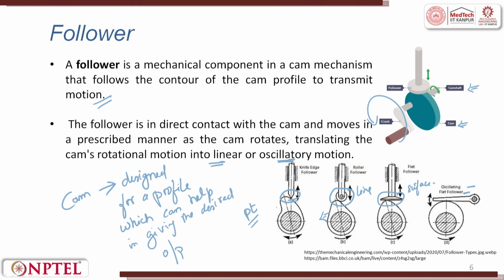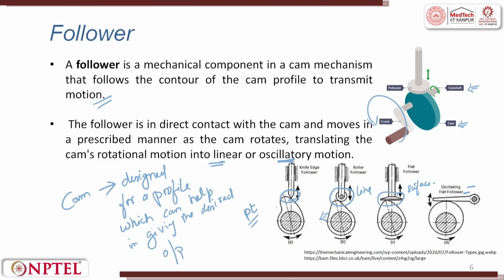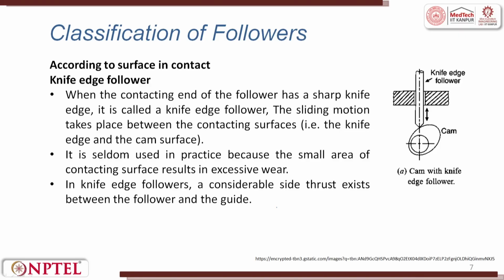Okay, what can be the cam material? It can be a metal, it can be non-metal such as a polymer. You can have this too. Can I have ceramic? Yes, but the only difficulty with ceramic is that it cannot take toughness or a fluctuating load. So, we try to give a ceramic coating on top of a metal and sometimes they call that ceramic cam and followers, but predominantly we will try to use metals. Again, in metals it can be ferrous base, it can be non-ferrous base. For example, it can be brass, bronze, steel, multiple things are used.